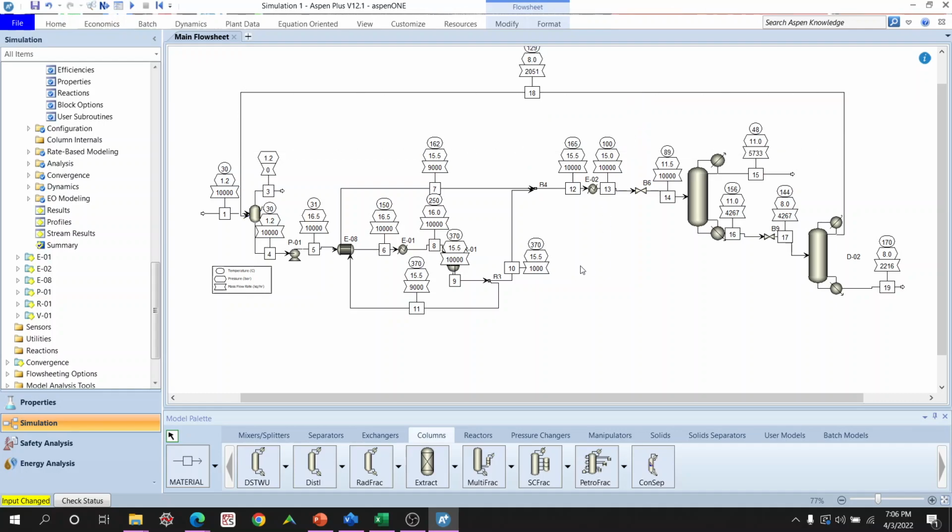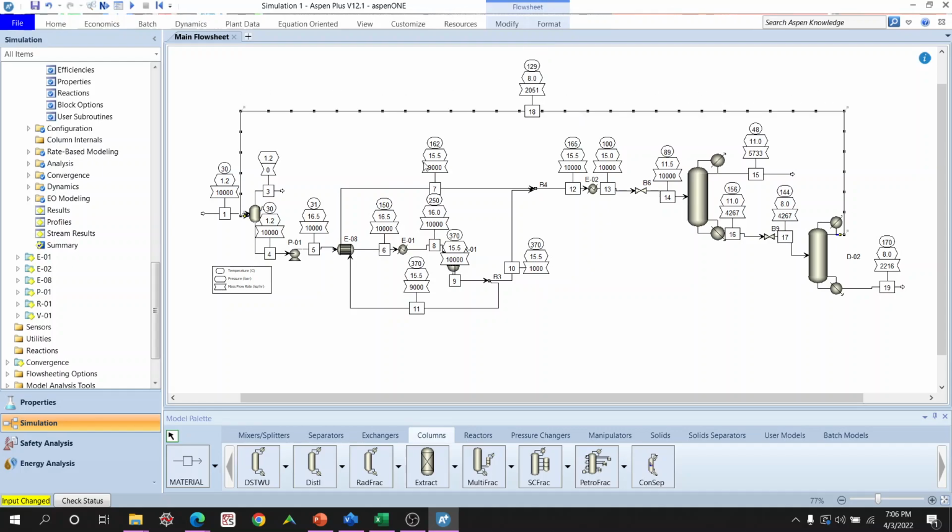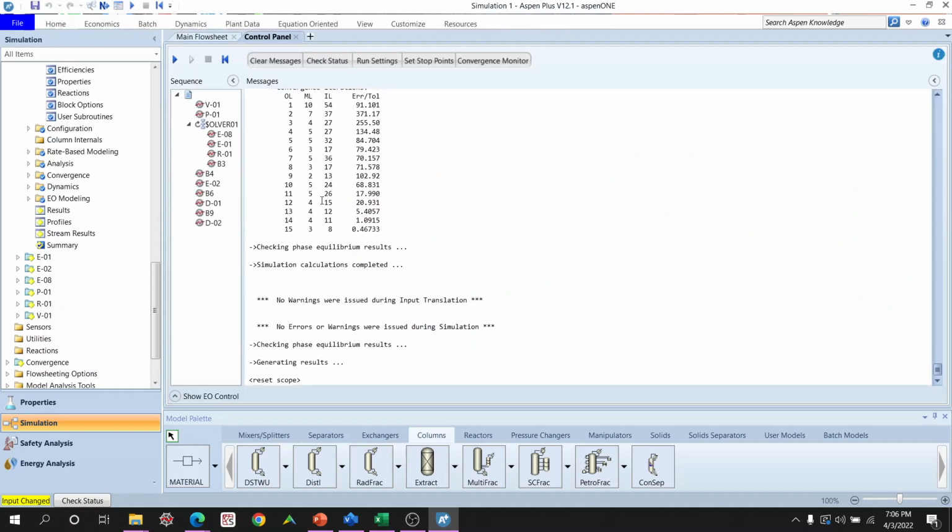It's now connected, so everything here will be changed automatically. Originally we have 10,000 going up. So what goes to the reactor? 10,000, but now with this additional 2,000 of the unreacted methanol, we will end up sending 12,000 of methanol more or less into the reactor. So that's a recycle.